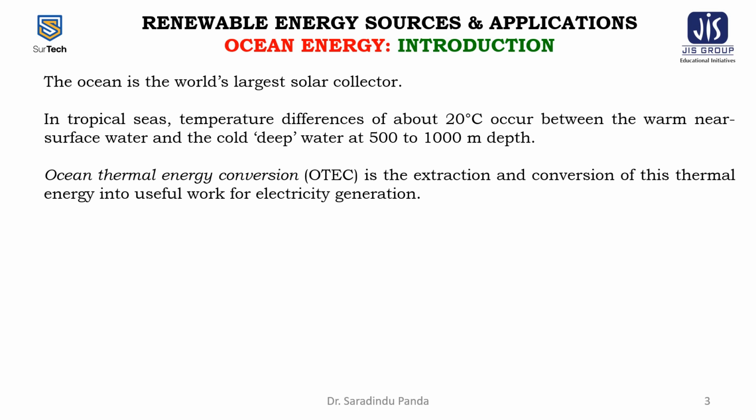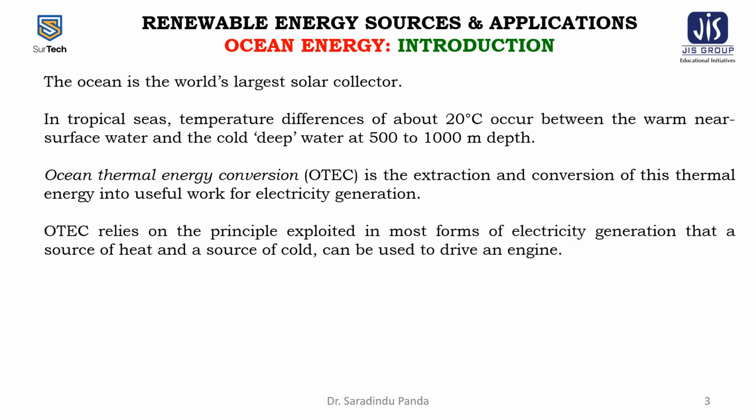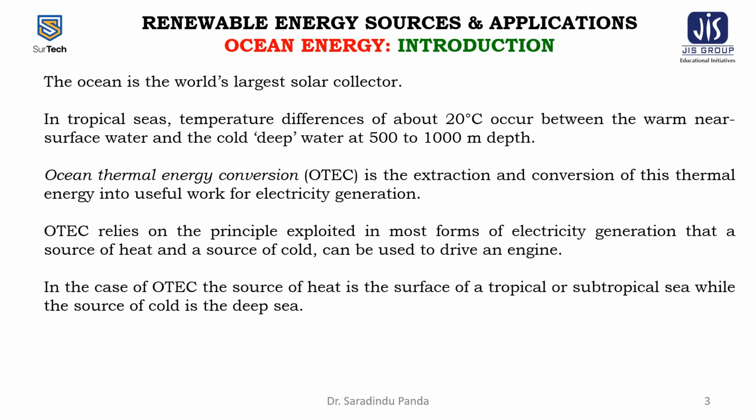Ocean thermal energy conversion is the extraction and conversion of this thermal energy into useful work for electricity generation. The OTEC relies on the principle exploited in most forms of electricity generation, that a source of heat and a source of cold can be used to drive an engine. In the case of OTEC, the source of heat is the surface of a tropical or subtropical sea, while the source of cold is the deep sea.